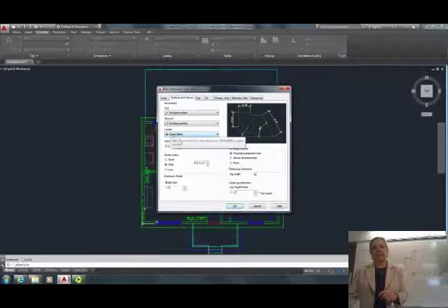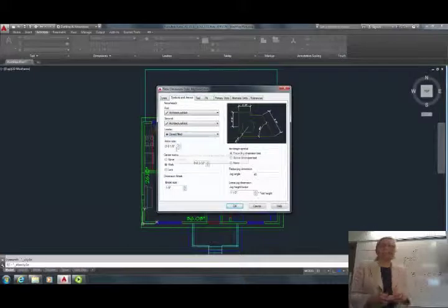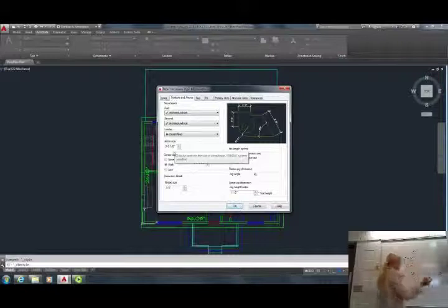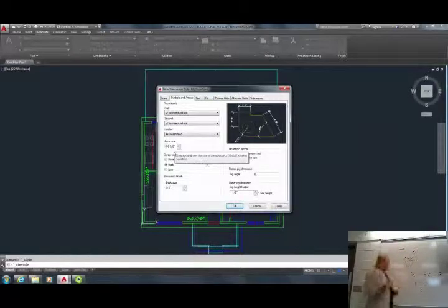Now, arrow size also controls the tick size, and this is another thing that I'll sketch here so you can understand. I don't have the erasing thing, but let's do the arrow here. Remember we did arrow like this, right? In drafting we did arrow like this, and it's supposed to be about 3 millimeters, 1/8 of an inch on our larger sheets.